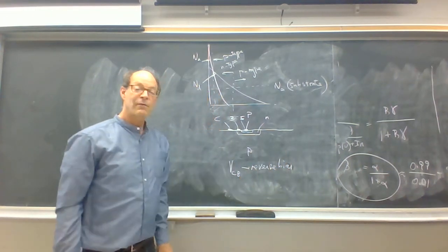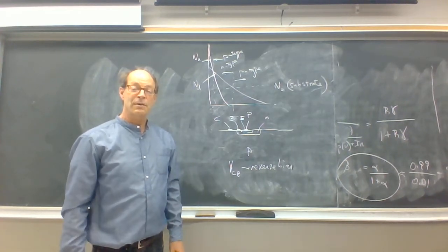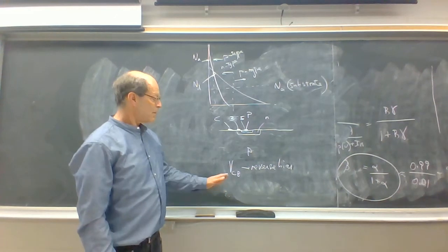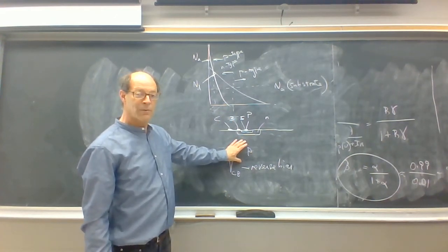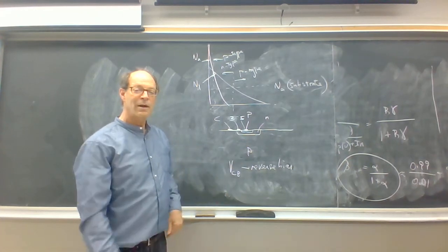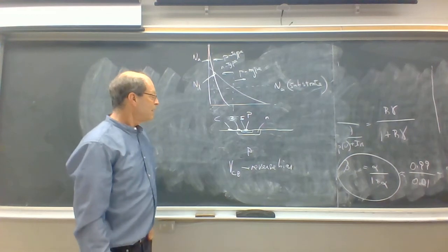And we want a relatively high breakdown voltage for the collector base junction. The breakdown voltage depends on the doping level, so we don't want too heavy a collector doping, to get a relatively high breakdown voltage at the collector base junction.